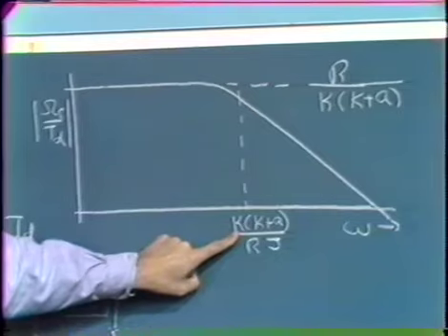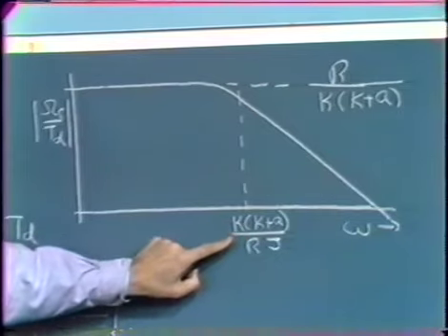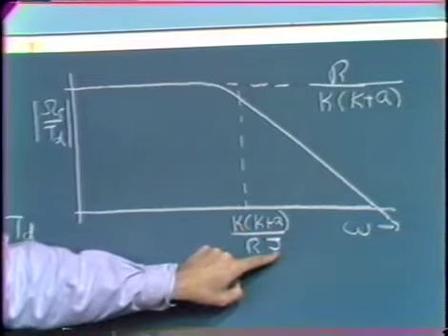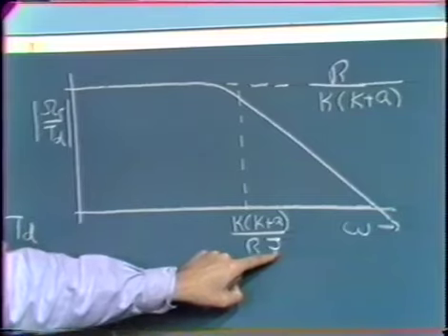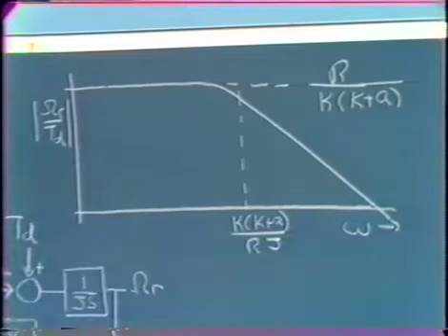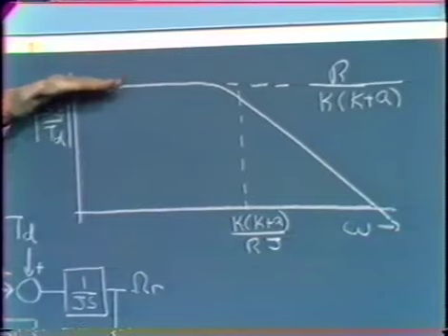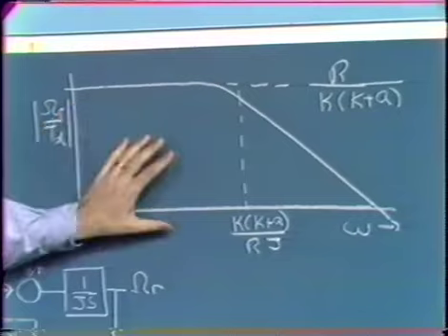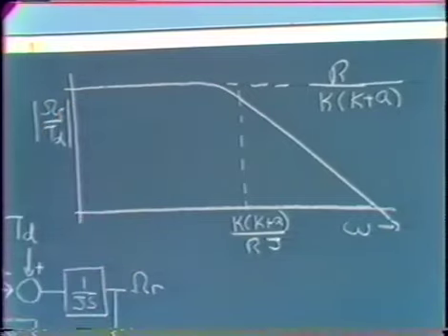And then there's a corner frequency associated with the system, and it involves a collection of constants, but the important point is that that corner frequency is inversely proportional to the total inertia. It's inversely proportional to J. And so if we added additional J, we build up our system, we adjust K, for example, in order to control our DC sensitivity to the level that we'd like to have it. We then can, by appropriate choice of J, ensure that the system crosses over before higher order poles in the system transfer function become important.